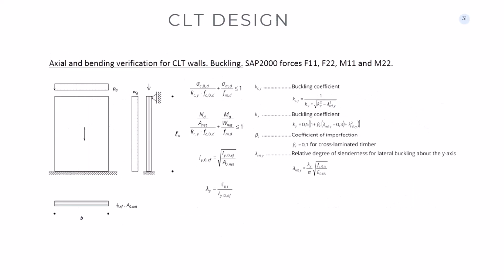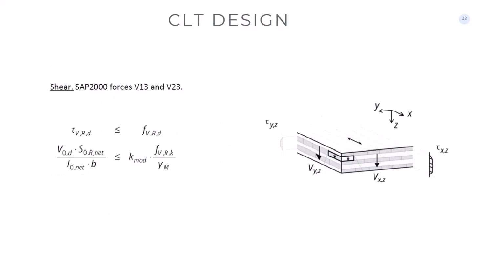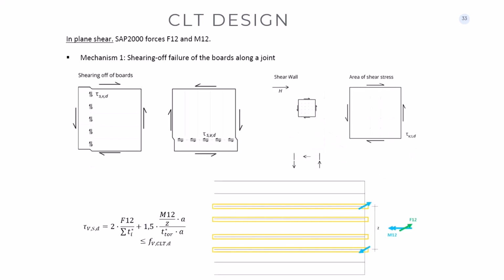Plus, of course, you have the problems of buckling, like in steel or concrete, and things that are very pure to this material. So here you see the typical formulation for shear stresses. But you can think of shear stress in two ways. It's the vertical cut of a solid element, but the same vertical cut is also associated with movements of the compression part with respect to the tension part.